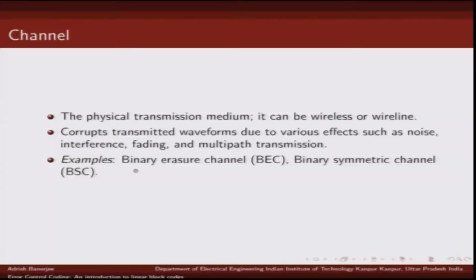And there are various models of channels which are very popularly used. In the last lecture, we talked about the binary erasure channel, which is a very good example to model a packet data communication system. Another channel model that we talked about was the binary symmetric channel. It is a very simple channel model, typically used to model an additive white Gaussian noise channel with hard demodulation. So, these are some examples of channel models.